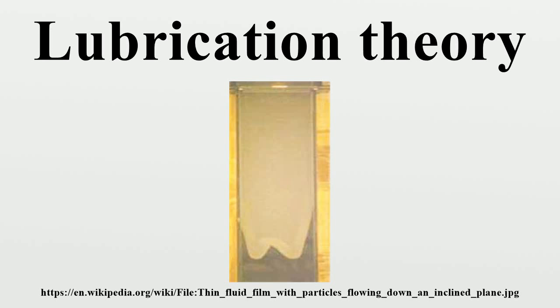Here p is the fluid pressure, u is the fluid velocity component parallel to the substrate, and μ is the fluid viscosity. The equations show, for example, that pressure variations across the gap are small, and that those along the gap are proportional to the fluid viscosity. A more general formulation of the lubrication approximation would include a third dimension, and the resulting differential equation is known as the Reynolds equation. Further details can be found in the literature or in the textbooks given in the bibliography.